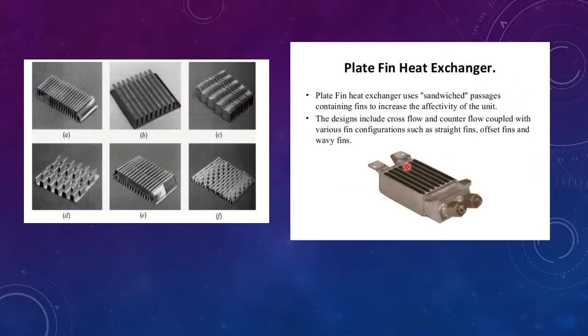Okay, next, the plate fin exchanger uses sandwich passages that contain fins like here to increase the effectiveness of the unit. The design includes cross flow and counter flow to couple with various fin configurations such as those beside here: straight fins, offset fins, and wavy fins over here.